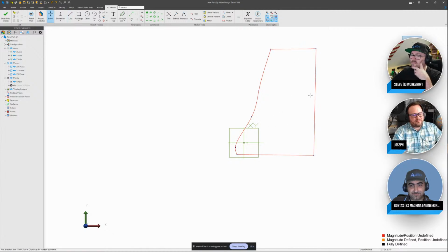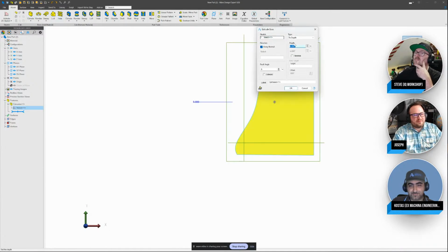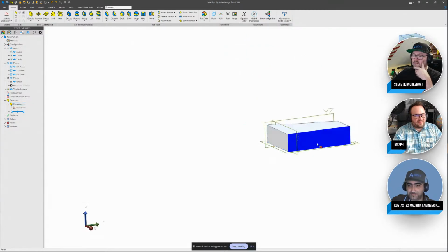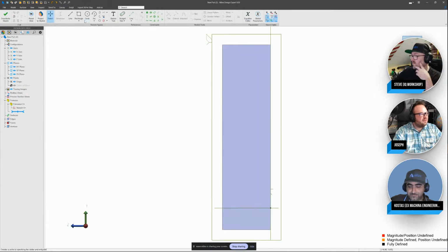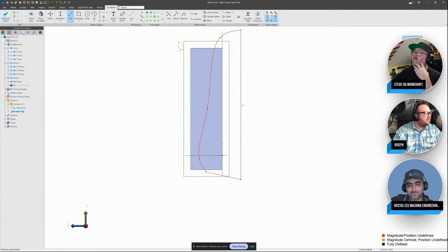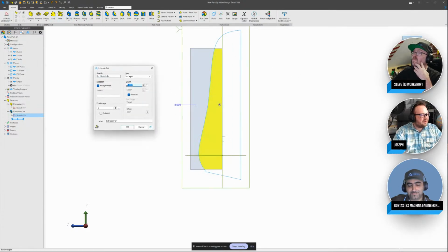I'm not really constraining my sketches, though in a serious project, of course, we would constrain our stuff. But here, I make a kind of difficult path in 3D space, and then we'll not extrude, rather, cut through that, through all.